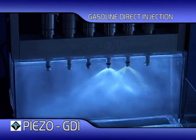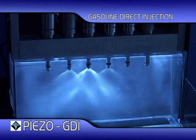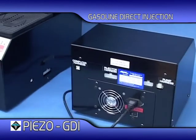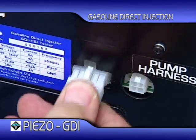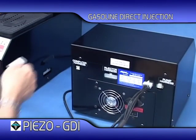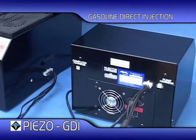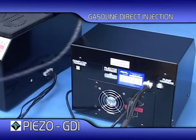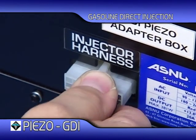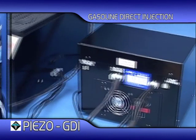As other manufactured piezo injectors are introduced to the automotive market, ASNU will of course produce flow rails and harnesses to suit them. This short clip shows how to connect the ASNU Piezo Injector Box to the ASNU Classic GDI system. First, connect the ASNU 605 adapter lead to the adapter box and then to the harness connector socket on the Classic GDI machine. Now, attach the ASNU 604 injector harness to the harness connector on the adapter box. You are now ready to test piezo injectors.